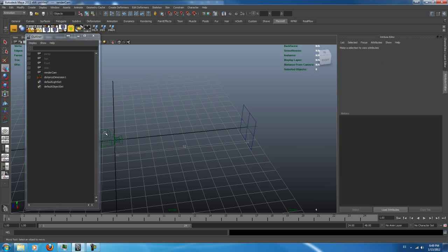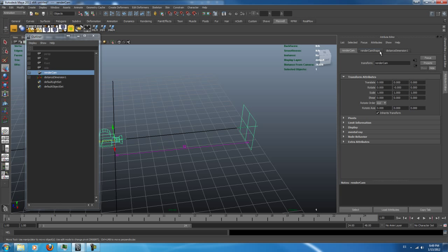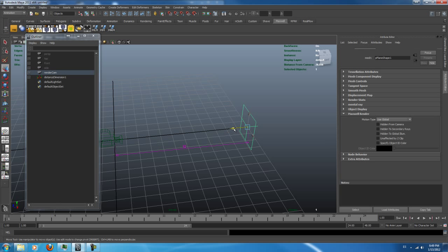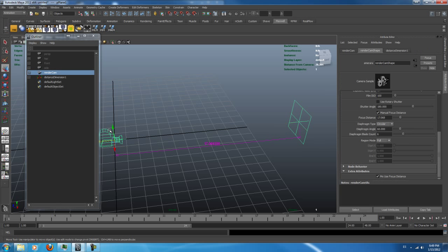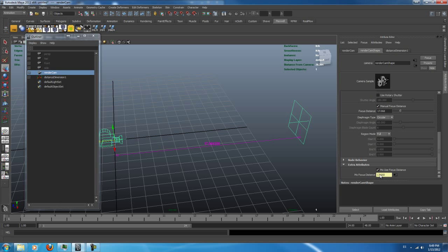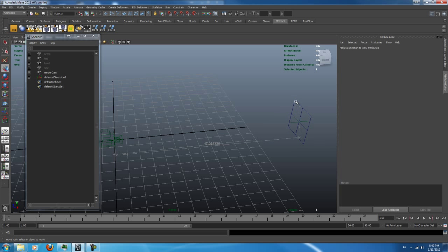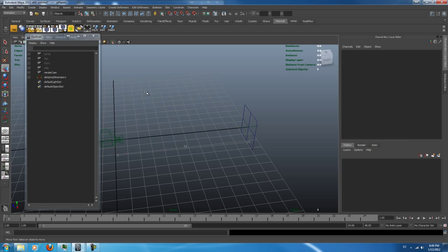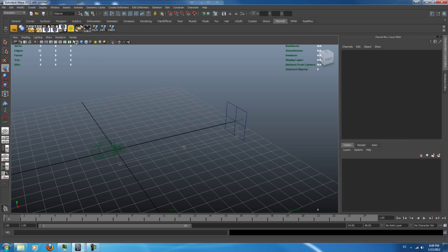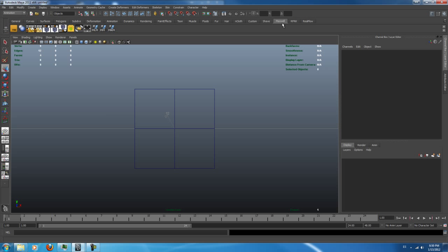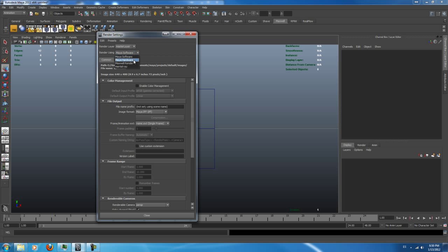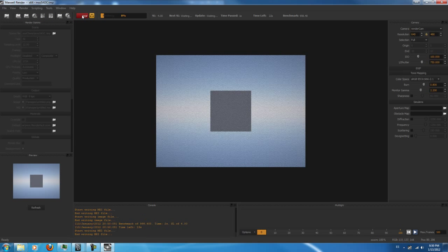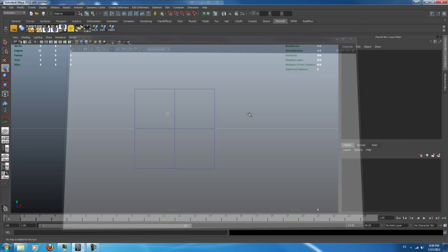So if we take a look, we just click and take a look at the Maxwell use focus distance. If I move my focus here in these values, automatically these values will be updated here. And if we take a look, for instance, let's place this focus plane again in 12. If we take a look through the Maxwell cam, we just select Maxwell Render and launch render here. Obviously the plane is there. We have some different options to hide the focus plane.